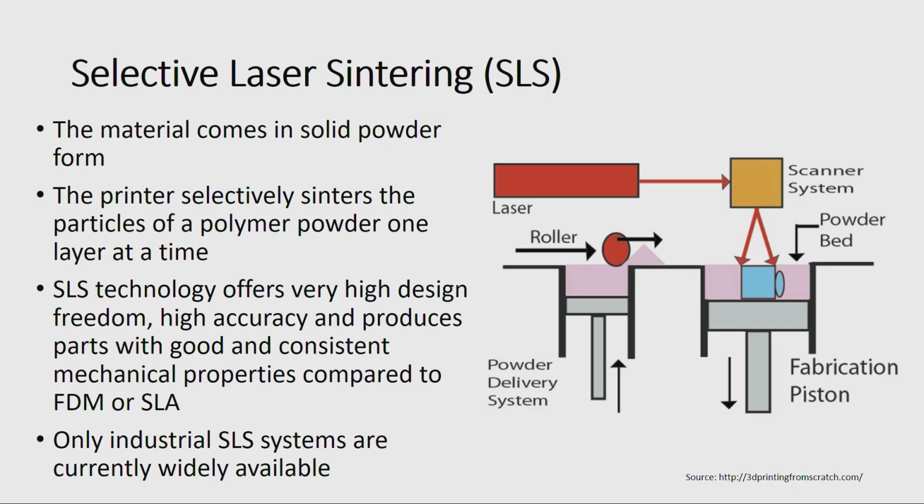A definite quantity of powder is transferred from the reservoir to the build volume, and the thickness of the powder delivered to the build volume is controlled. The roller will move from left side to right side, and again it will come back to the initial position, such that the uniformity of the layer delivered to the build volume is consistent.